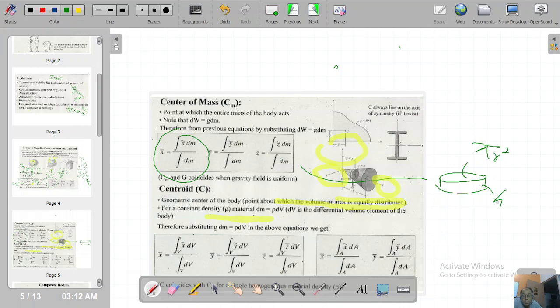And I can tell you the centroid of this disk will have two coordinates, as I can very easily say: x bar will be 0 for this centroid, and y bar will also be 0. You can say x bar will be 0 and z is on the top, so I will not say this, but I will say z bar will also be equal to 0, but it will have some finite value in y bar which we need to calculate, maybe any value 4, 5, 6, 3, any value. But why? Because it will not have any centroidal coordinates along the x and z.